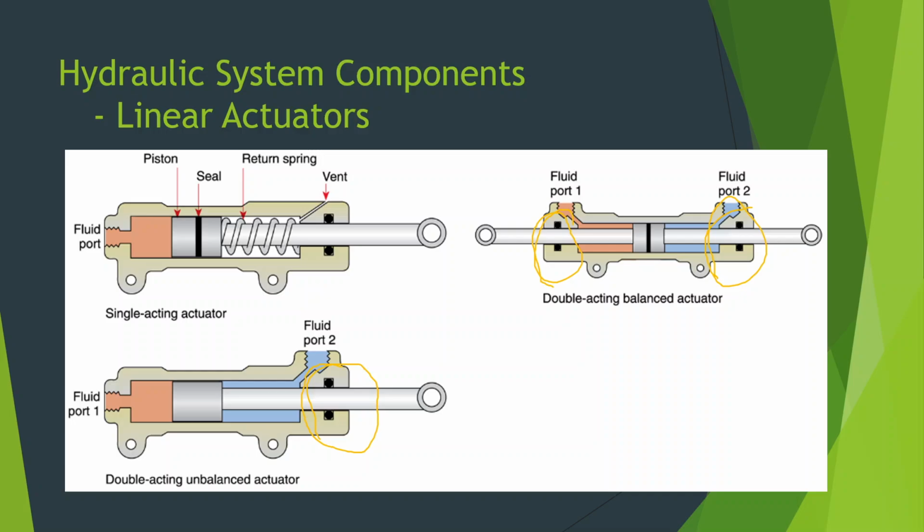What that means is hydraulic fluid does go out. Say this bottom actuator, the double acting unbalanced, when that extends, a small amount of fluid is going to go from inside the actuator to outside. And over time, it will be enough that you may get a drip or two that ends up on a panel or something. Every aircraft I worked on commercially, because we didn't repaint them as often, the ailerons and the elevators, if you looked right below where the actuators were, almost always had some paint missing.